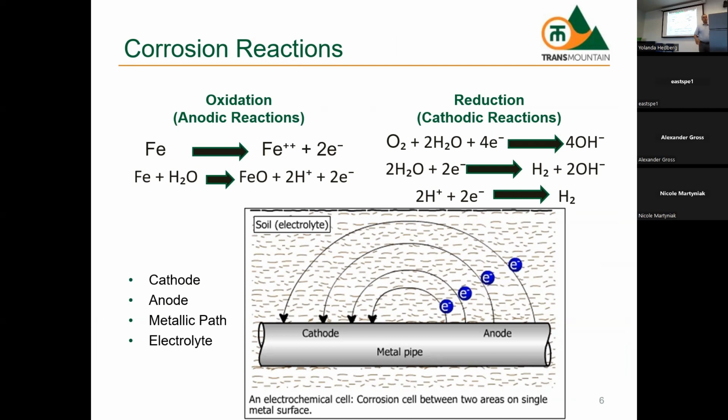So we talk about anodic and cathodic. Anodic is where the corrosion is occurring, and you can see in the chemical reaction, why is the pH so low? Because of the H plus. Yeah. That's correct. Proton. Okay, so you can see when you have corrosion, it's very acidic because of the chemical reaction that's creating the hydrogen ion. Okay, that low pH, that acidic environment in direct contact with the metal is indicative of the corrosion.